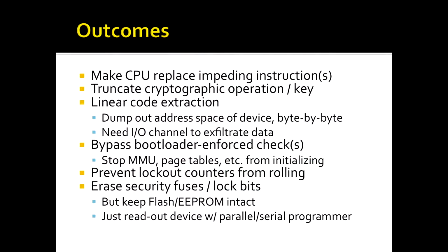In some cases, you can prevent lockout counters from rolling. So if it's a secure crypto memory or something like that, where you only have so many tries before you're locked out of the device, if you glitch when it's recording or decrementing your try counter, the number of tries will never change. So you can just keep doing your malicious activity over and over again without the device finally reaching zero and then erasing itself or halting or something of that nature.